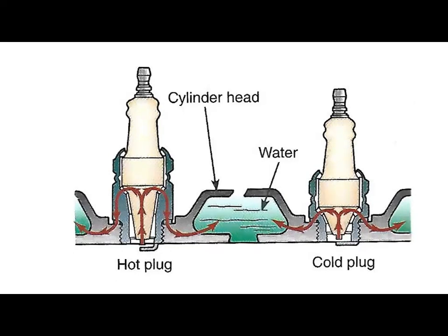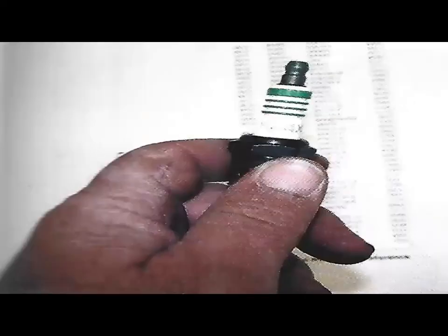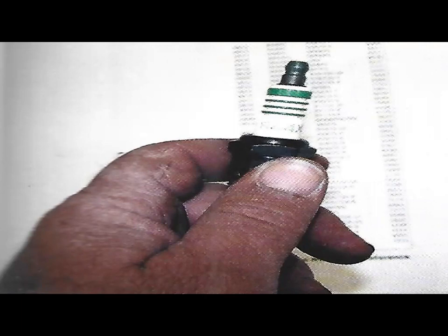In a spark plug with a colder heat range, the distance is shorter from the center electrode to the point where the insulator contacts the shell. This design allows faster heat dissipation through the spark plug so the electrode's temperature is reduced. On many spark plugs, the number on the spark plug indicates the heat range. A higher number represents a hotter range spark plug.